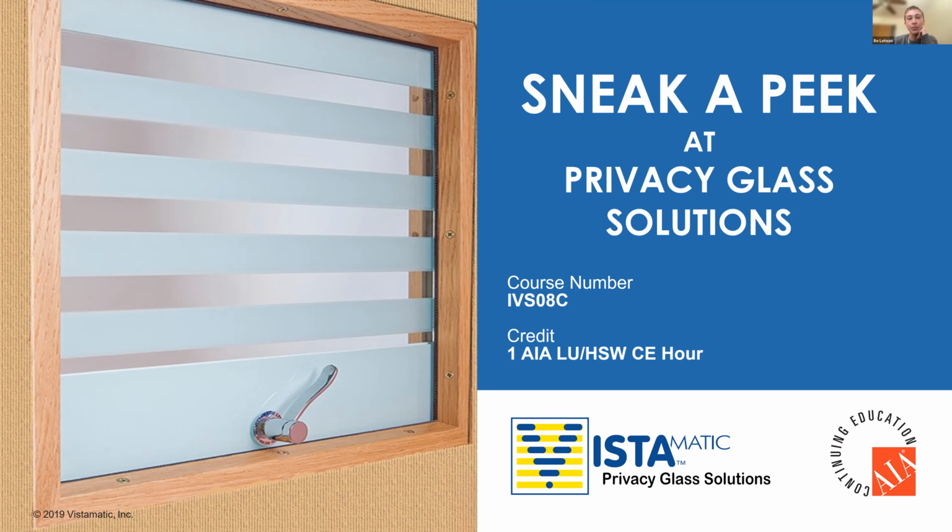And then another person asks, will the product be yellowing throughout its life cycle? No, shouldn't have any kind of yellowing. This product as a standard is going to be more for an interior application. If you did want to use this as an exterior application, and specifically talking about the electric switchable privacy glass, it can be customized into what's called an IGU, or an insulated glass unit, where you can have low E to keep heat in or out depending on where you are and what the application is. But that would also give it a higher lifespan if it's being used in an exterior application.